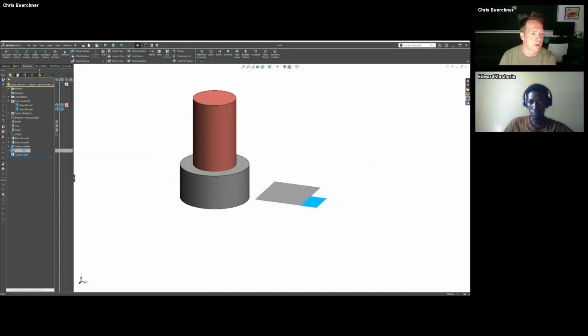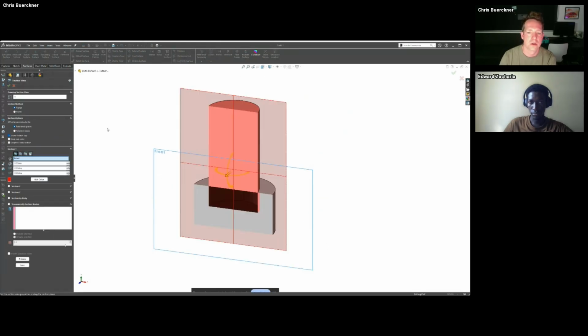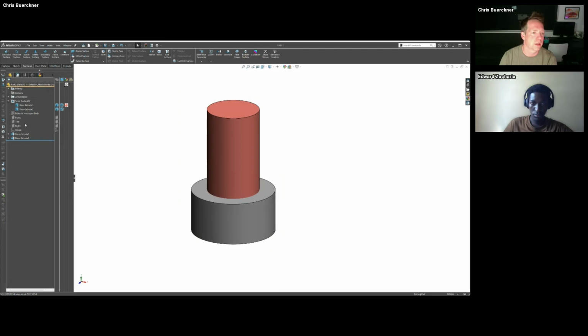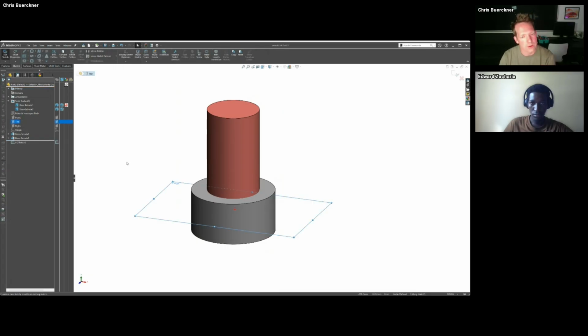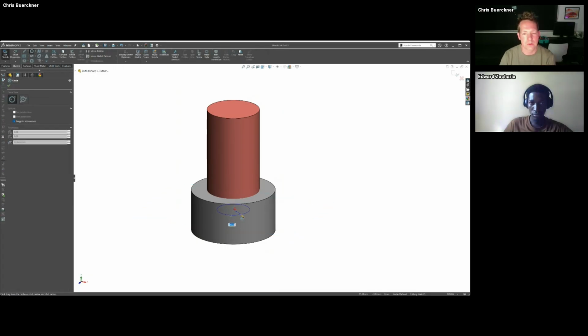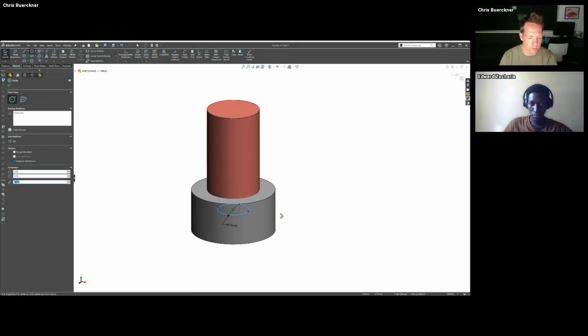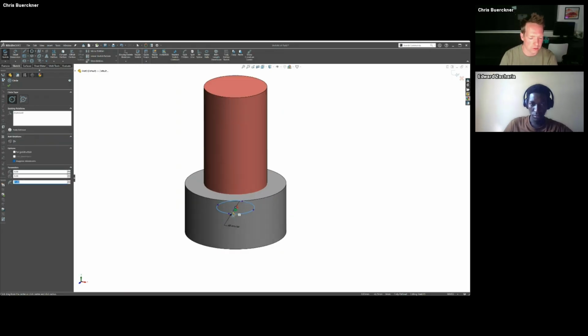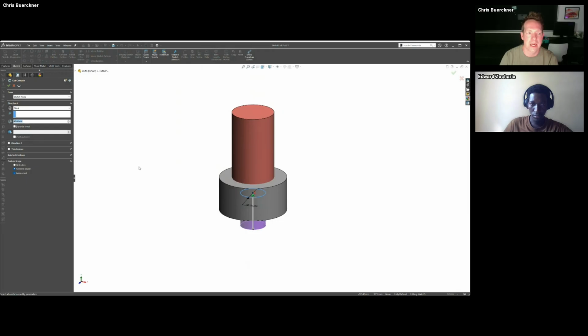Okay, now I'm going to get out of surfacing. We are just focusing on the solids. So if we do that section view, we can see, again, that overlap area, which is down here, the dark area. Now, what we can do then in the multi-body environment is, let's say I want to do a cut through all. So I'm doing a circle, I'm doing an extruded cut through all bodies.